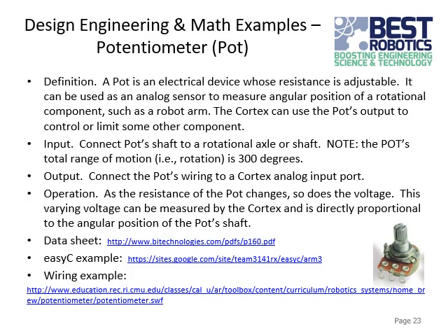Here I just wanted to tell you about another part you have at your disposal, the potentiometer. I wanted to highlight this one because it doesn't get a lot of use, but it can be useful at times. I think a lot of people don't understand it very well, so I wanted to talk about it. Some people call it a pot for short. It's a device whose resistance changes as you turn the knob on it.